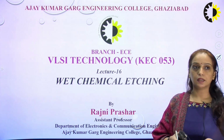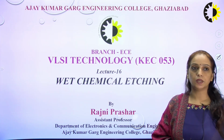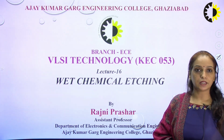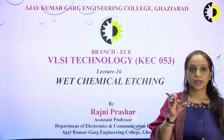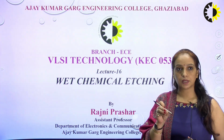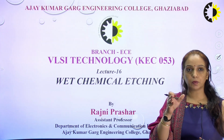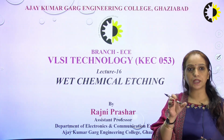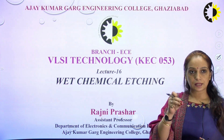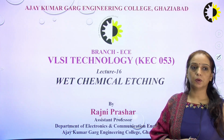So in this lecture, and in the upcoming 2 lectures, we are going to become familiar with the next processing step, that is etching. The windows which we have created with the help of the photolithography process, from those windows we have to etch the silicon dioxide layer, and below that silicon dioxide layer, in the silicon, we have to dope the impurities, right.